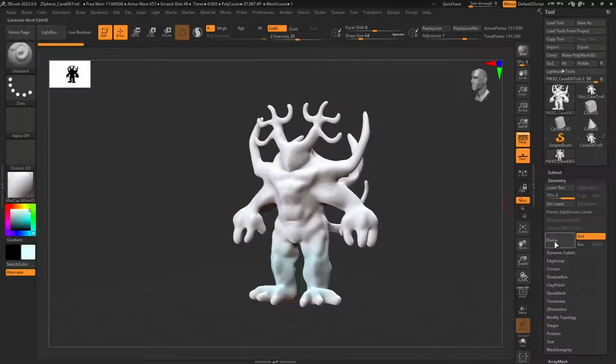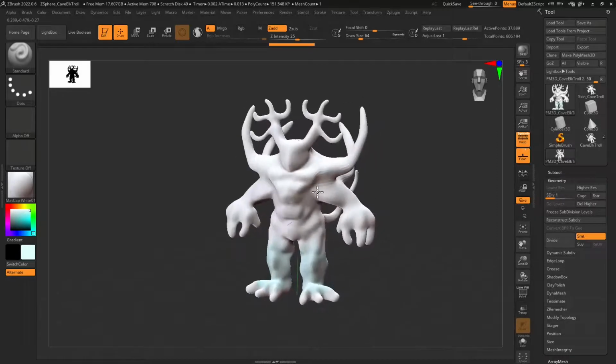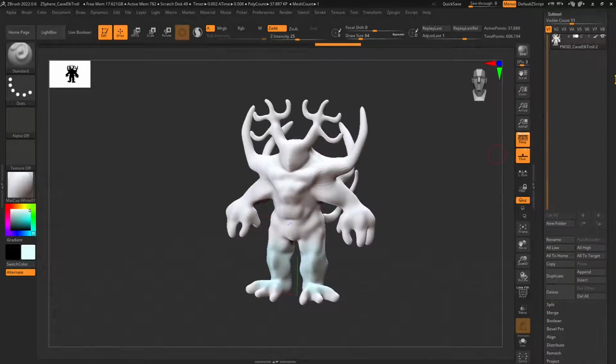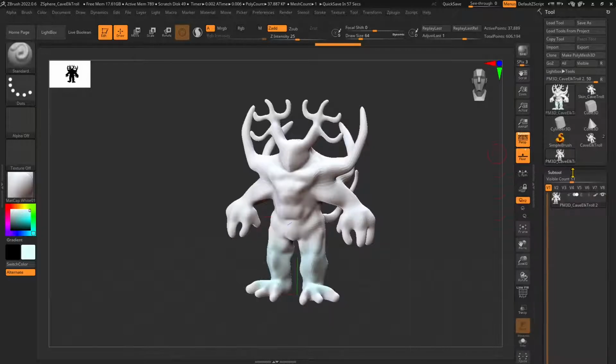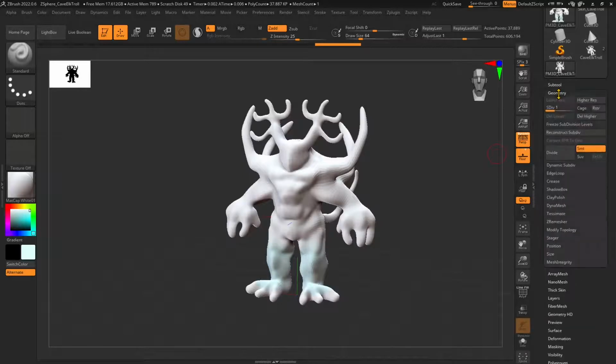Now, when it comes to export, I think one of the most important things is to have subdivisions, because if you have subdivisions, you can decide whether you want to export in a high poly fashion or low poly. So you can essentially manage the resolution, the polygons. And this is important because in some applications you can use a really high number of polygons.